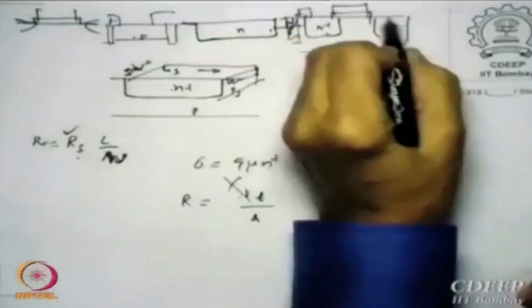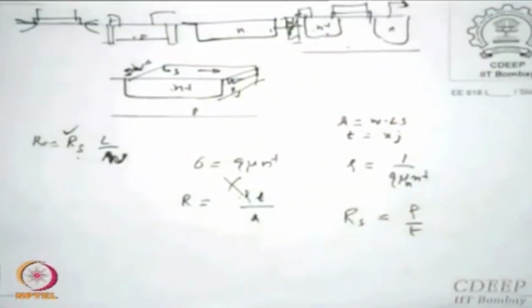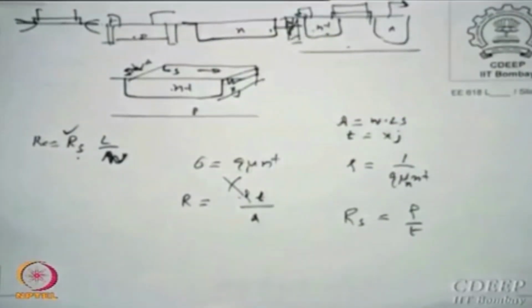I have a MOS capacitor sitting there, but there are other capacitive methods also. You can also have a transistor and ground it on both sides. This is a good capacitor. If I connect gate to the source, I will make a diode out of it. I showed you diode connections earlier. So I don't make any additional device in the ICs, I only convert my MOS technology areas into a variety of components.